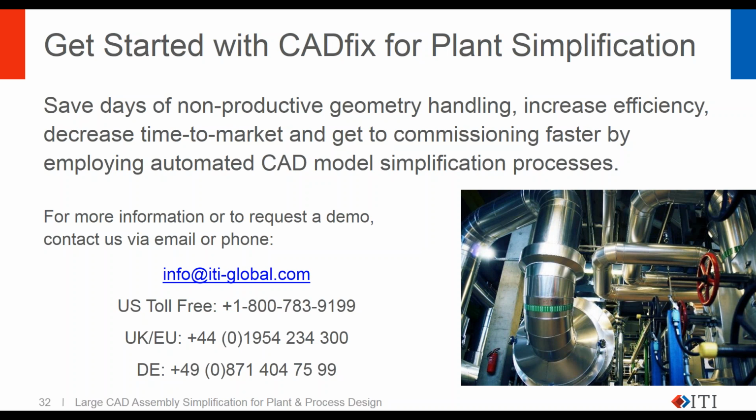Okay. One last question, and this relates back to the NX question. In the case of NX format as input and JT as output, is it possible to maintain attributes present in the original NX file? Okay, the attributes that we support are the color, the layer, and the CAD label.